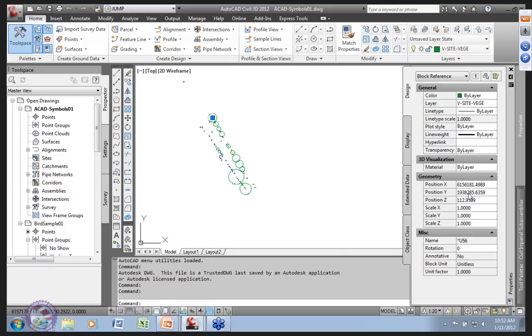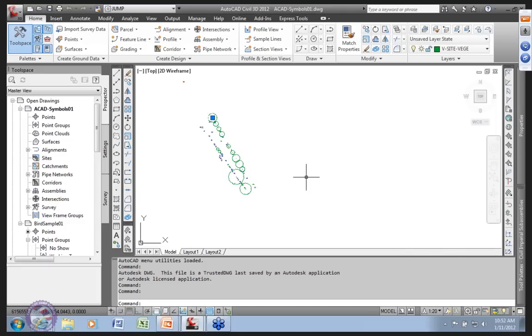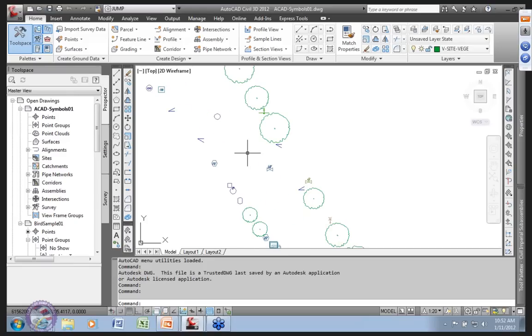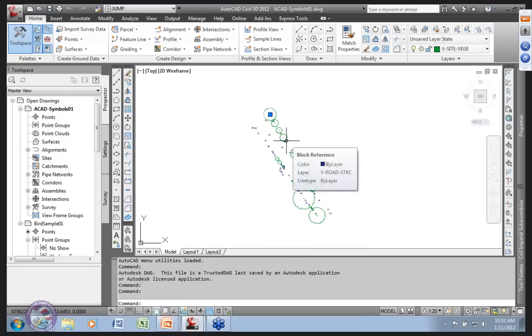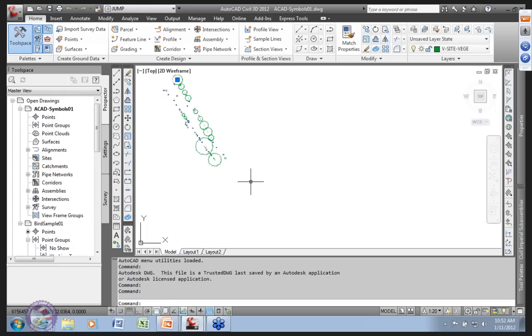Your point style actually controls that over in Civil 3D, whether it's employing real Z's or not. So you can open a template that has all the point styles defined to use 2D, flat, be on layer 0, or be on a specific one if you want them all flattened that way, or you can post-process. That gets you your symbols out. Now we've got the figures and the symbols out, in all the right locations with the symbols I want.